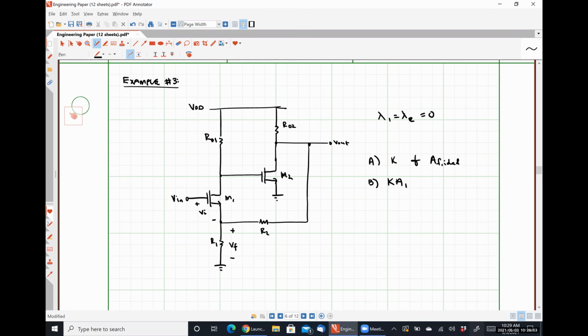So one means by which we can determine the feedback factor is to just say, what if the open loop amplification was infinitely large? What if our amplifier was ideal? That will allow us to determine our feedback factor for the system. So how do I accomplish that feat? In practice, all we have to do is pick one of our two transistors. I'll do it for transistor M1 because it makes the math a little bit easier, and just say that its gain, which is gm times VGS1, or well, I guess that's not really its gain, but we are effectively scaling that source to be infinitely large.